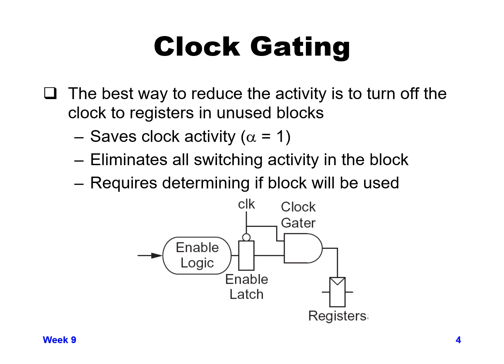So that will lower your average activity factor for all of your logic for however many cycles you aren't using that logic. So this is probably the number one way to reduce your dynamic power consumption, to use clock gating as much as possible anytime that you know you're not using logic.